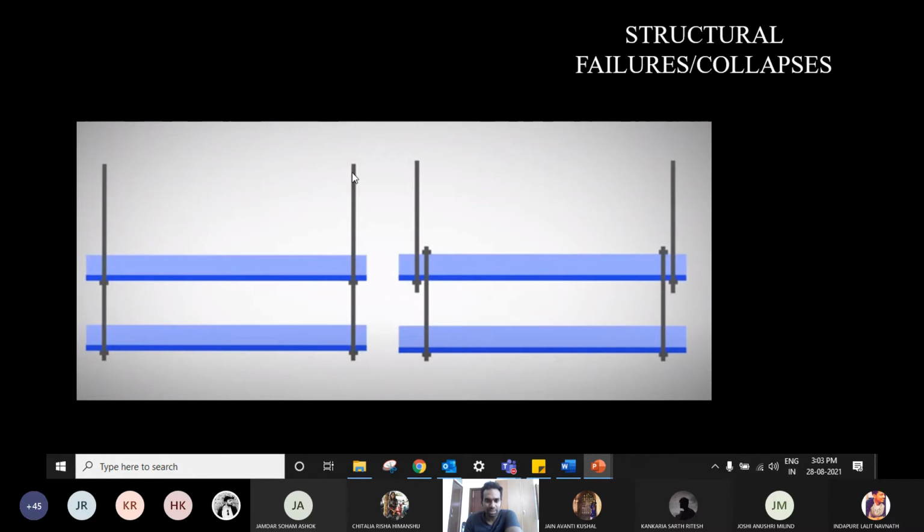If you look at this section on the top, which is above the walkways, it's the same. It's experiencing the same load, okay, in both the cases. So your tie rod did not give in. What happened was your bolt here, this connection over here, instead of getting only the weight of this one slab, now is experiencing the weight of both the slabs by this simple arrangement.